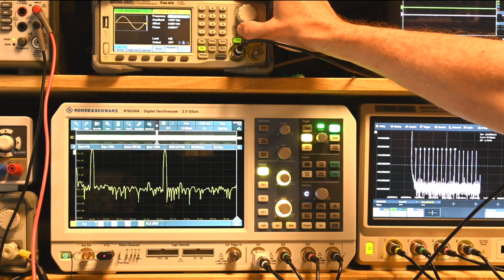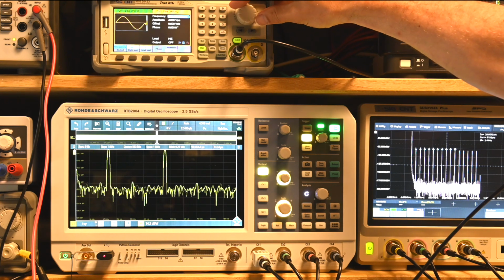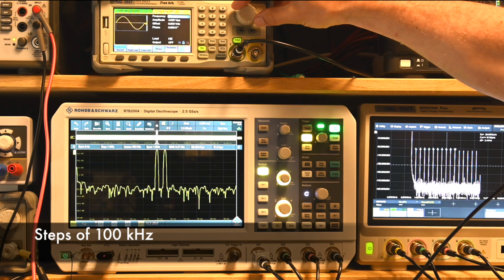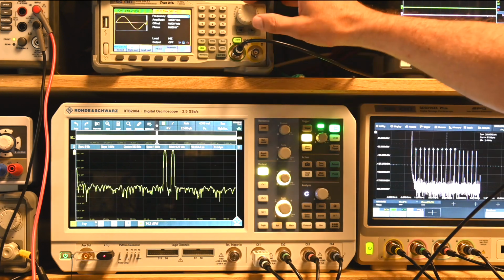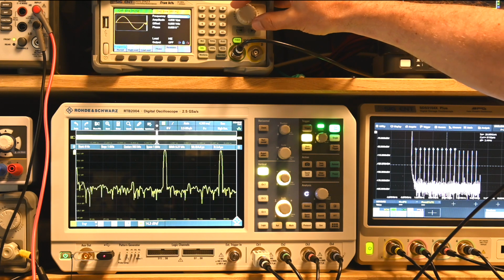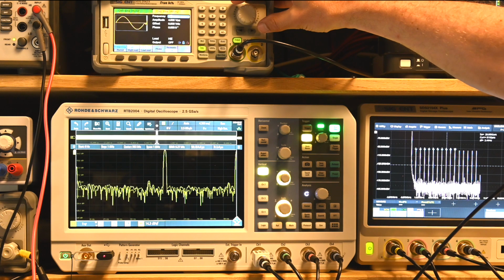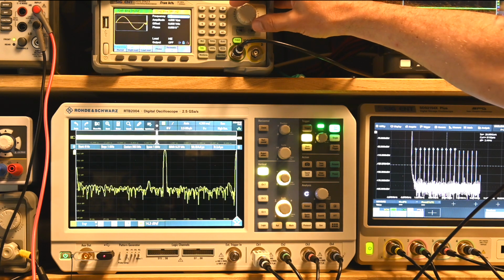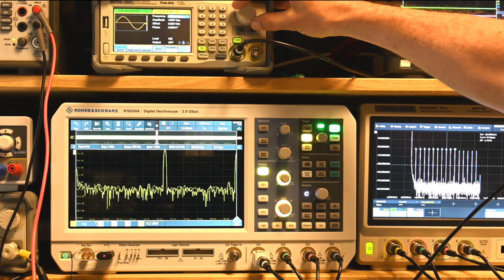Now let's play with the tone at channel 2. I'll increase its frequency in steps of 100 Hertz. So we see it going up. We see it jumping over the other tone, the one of 550. So we're jumping from 500 to 600 here. We go up, and now we come to the point where our tone is disappearing from the view, because we're only looking up to 1 megahertz and we're feeding in 1 megahertz now. But I'll continue, and for a while we're not going to see anything at all.